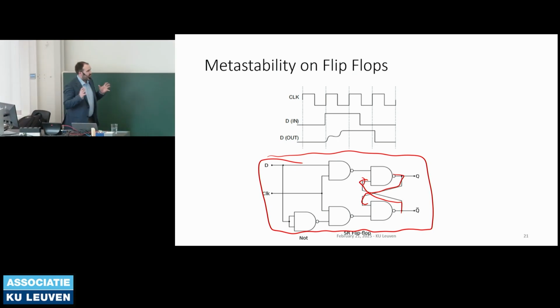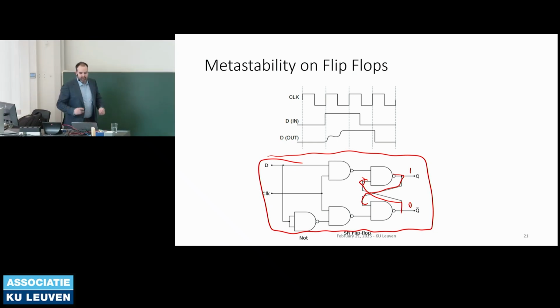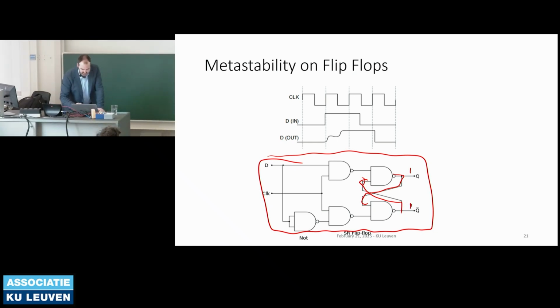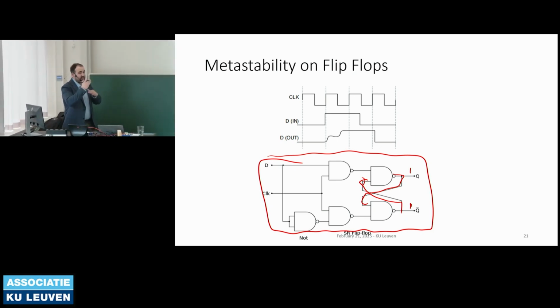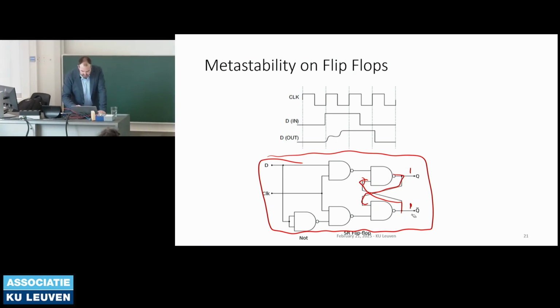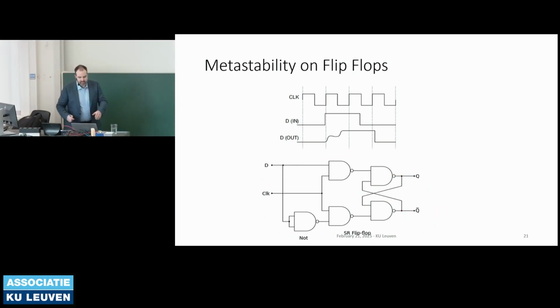Internally, these should always be opposite, 1 and 0, or 0 and 1. If they enter an invalid state, it eventually has to resolve to either one being 1 and the other being 0, but there's a time where they fight each other. So we call this a metastable state. It's not stable. It has to resolve to a stable state.